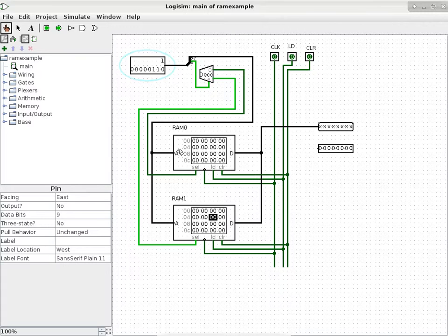That's because we specified the right address already. The decoder is doing its job as well. It's taking the most significant bit out of the address pins and using that to turn on the correct RAM chip by activating the right chip select. Are we still doing okay so far with this exercise here?